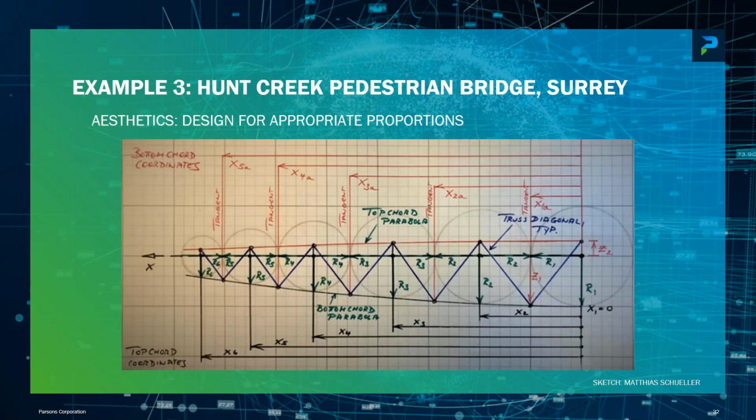Now, how do you deal with these diagonals in the truss, because you have this kind of fish belly system, and fish belly systems have the problem that when you keep the spacing of the nodes equal, the angles get more and more shallow as you get to the end. And that creates issues, especially at the ends. You have large shear forces and then very shallow and long members, and you don't want to see this in long members. So the idea was, how can I keep the demands in the members so that I can use the same cross section everywhere for the diagonals. Where I have the long members, I want small shear forces, and where I have the large shear force, I want short members. And you can say, let's try to make them all with an equal angle, but this doesn't look so good.